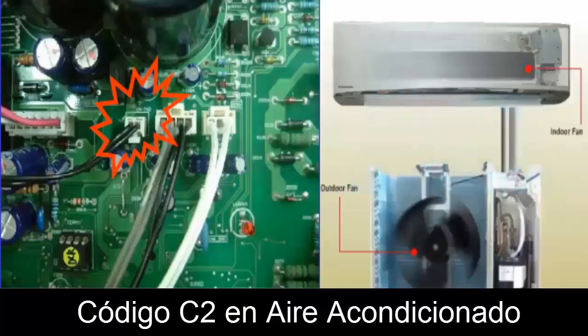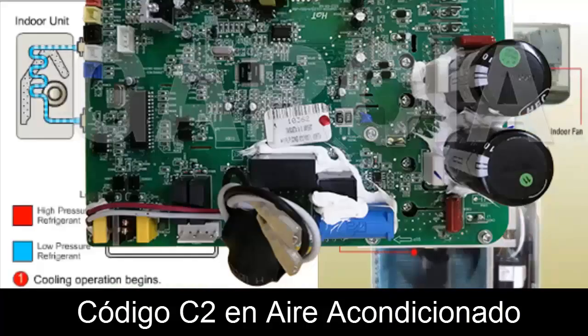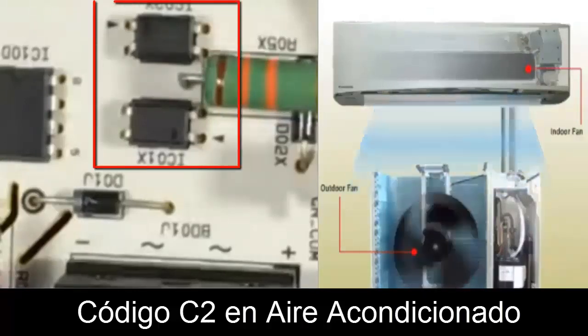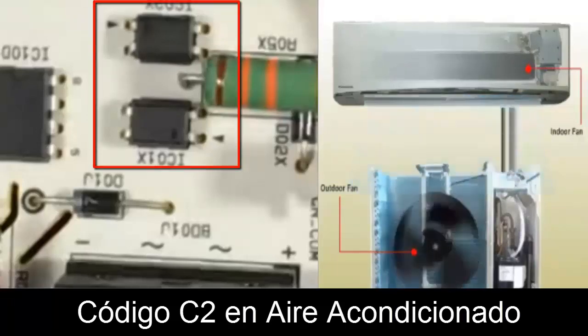E. Perform a visual inspection of the electronic boards for damage, and replace any components that appear to be in poor condition. F. Many communication problems between units are related to optocouplers located near the signal cable connection.